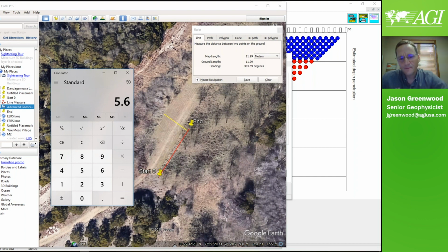So in 2D, there's more bang for your buck, there's more exploration depth than with 3D, because there's costing to having 28 electrodes or 56, having all those cables, the manpower to deploy it, so that's a big consideration to doing true 3D, or what we call pseudo 3D.